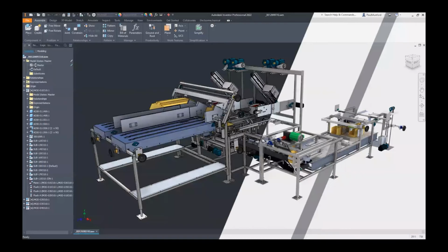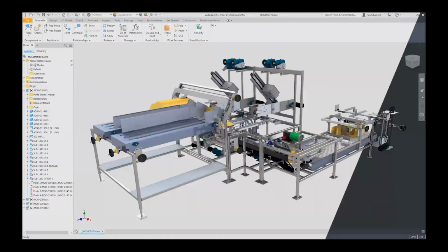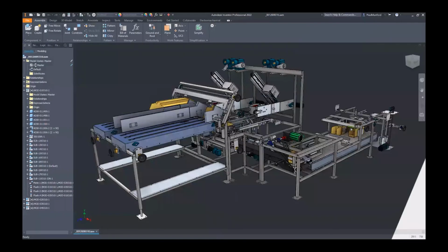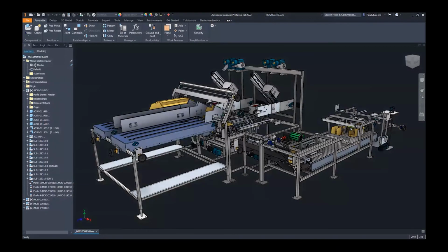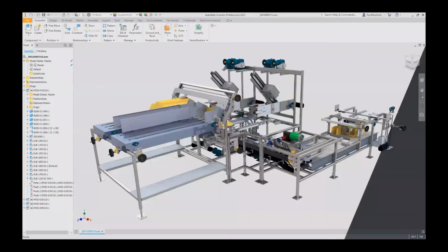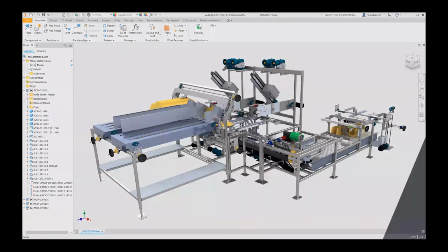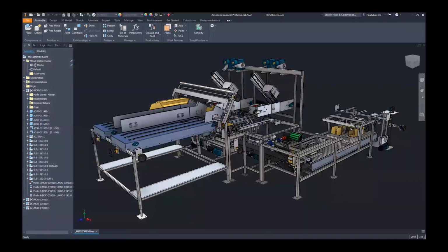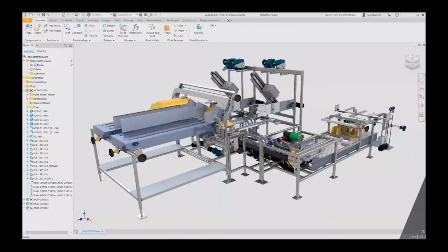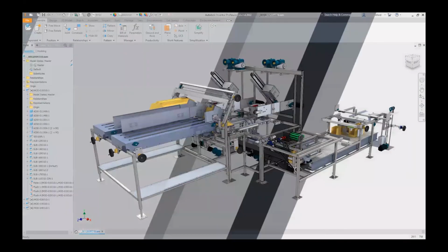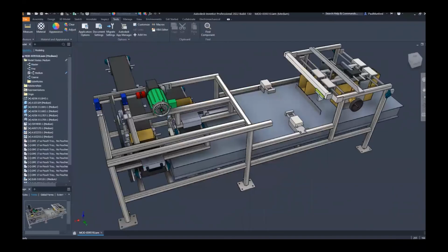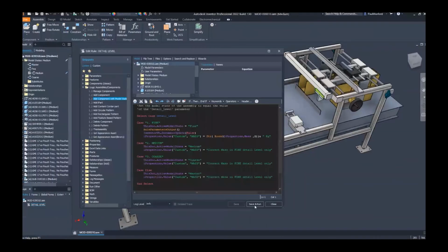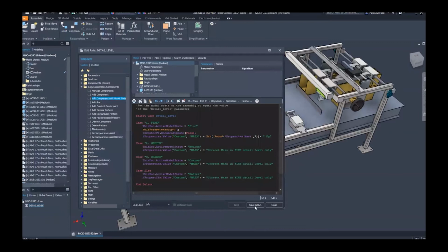Okay, with regard to the dark theme, this was introduced as a technical preview in 2021, and many people tried that out. The big problem was that when you switched over to the iLogic browser, for instance, it went back to the white theme, or the light coloured background. So this has been improved, and certainly Autodesk are still working on some of the tools in this regard as well. So the dark theme is being applied to more and more tools as we work through. And again, just a reminder, if you haven't used that in the past, you'll find that under the tools menu under application options and inside the colors tab. But again, I will give you a quick rundown on that in our demonstration shortly.